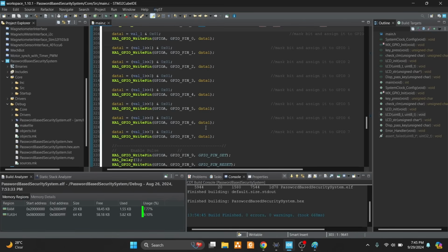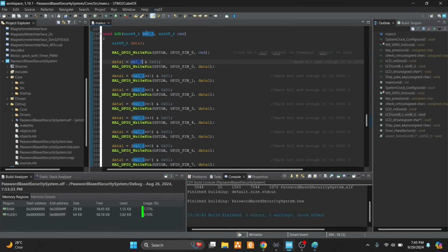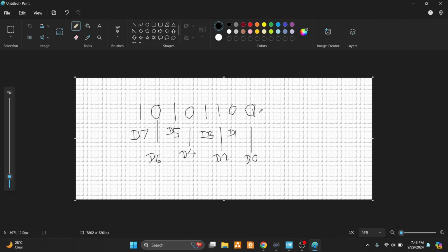So what we are doing in our program is we are getting the data, whatever 8-bit data is here. We are ANDing with 0x01. All these other bits will not be considered basically for now. Whatever the value over here, either 0 or 1, if ANDed with 1 we will get the same value, right? So that is the basic ANDing principle. We know the truth table for AND operation, we get 0 0.